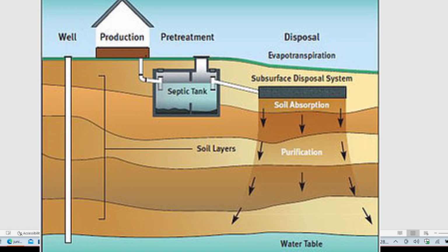The other thing is, if you have a septic tank as a wastewater treatment unit in your home, you should not use disinfectant, because remember, this is a natural process. We call it biological decomposition. It uses anaerobic bacteria for the process. So if you use disinfectant, then that might affect the well operation of your septic tank.